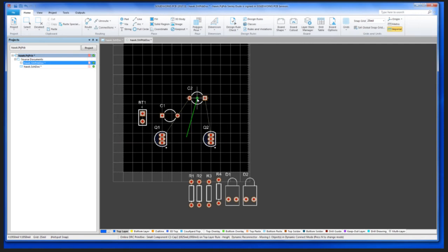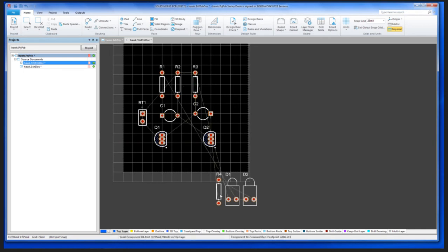Get our capacitors in place here. And then I'll move to pulling in all of my resistors. So that I can see by the guide wires the location that I need the pins to be and follow my circuit wiring diagram.